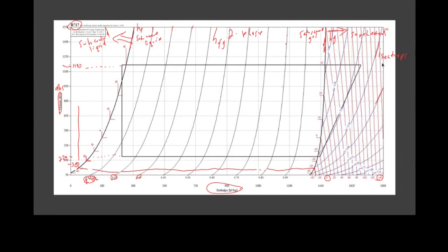And so, we could factor in isentropic efficiencies, but for the sake of the third class, what we're going to do is just assume that compression is adiabatic. And adiabatic, what is it? It's isentropic, constant entropy. So these are very, very useful lines if we're trying to trace the compression process, because it will follow lines of constant entropy.